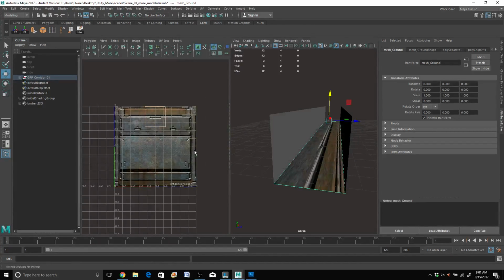Alright, cool. Now, if you're unfamiliar with the UV texture editor, you see this little tan square thing here? That is our UVs for this guy here. That is the reason why it looks super stretched. It's not taking up this entire 1x1 Cartesian spot, which is where our texture is at. So we're going to want to change the scale of our UVs, right?